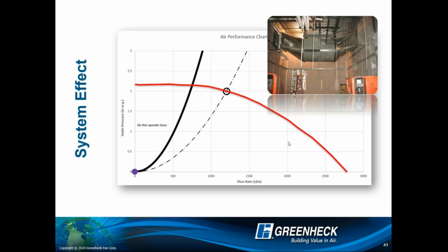And if I were to project what would happen to the fan curve on this installation, here I'm just going to give you a representation. That fan curve that I made as a manufacturer doesn't even exist, right? It's gone. The air's not moving in smoothly. It's not leaving smoothly. All that data I have, gone, right? So here I'm representing just some really weird fan curve, what could be.